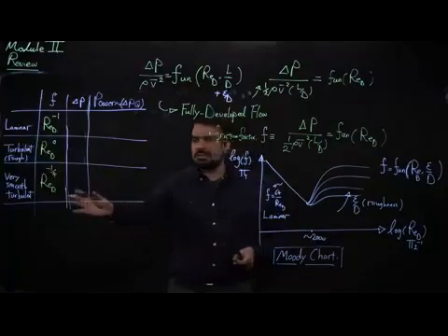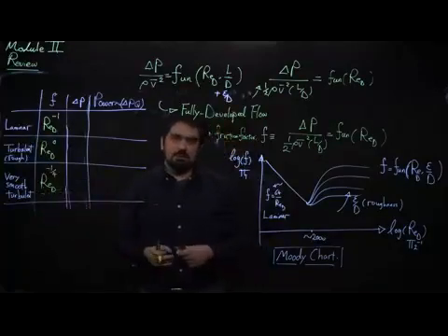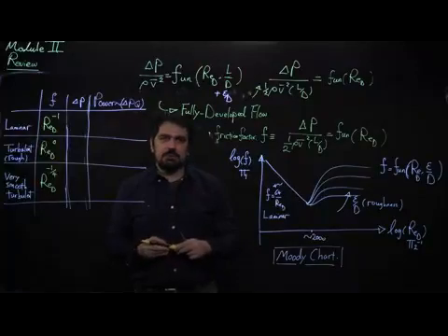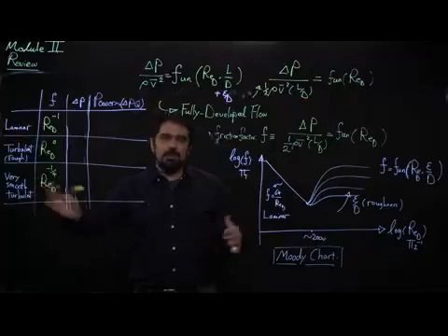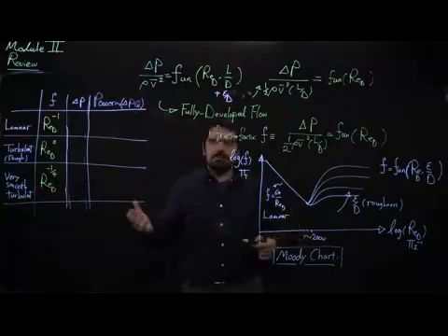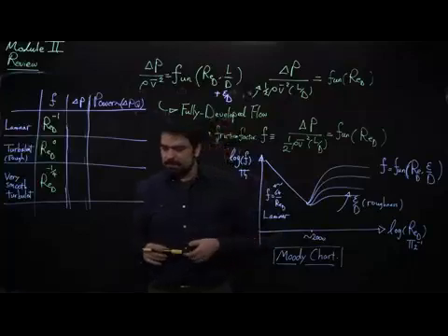This is a result that is given to you from the Blasius solution of the turbulent boundary layer inside a pipe for the case of 0 roughness. You are not really asked to know it, but if you would like to compare things, I'm writing it on the board so that you see a relatively nice comparison between these different cases.